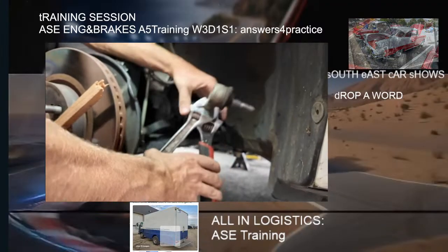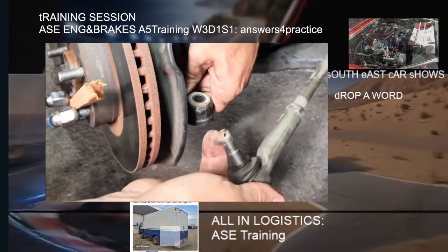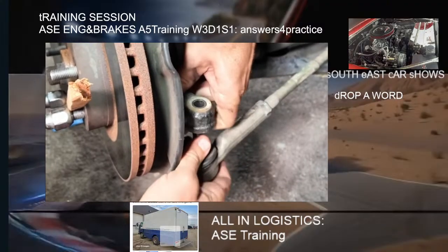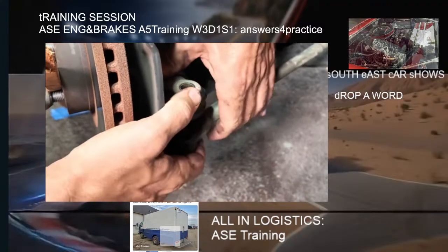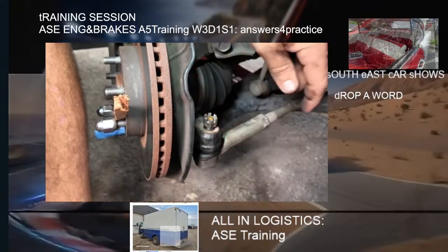Wow, that's really tight. If it's really tough, like this one is being right now, I'm actually gonna go ahead and slip this back into its hole on the hub really quick. That way that'll kind of hold it. I can even throw this nut back on, a couple threads.